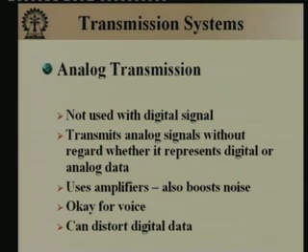So, it uses amplifiers, but the trouble with amplifiers, rather than the kind of regeneration that is possible in the digital world, is that it also boosts noise, whereas in the digital case we could take out the noise and regenerate the original shape of the signal. Here we can amplify it, so that if the signal becomes weak, we can make it stronger, but whatever noise is coming with the signal also gets amplified. So, this is okay for voice, but using analog transmission for digital data is usually not done, because we have so little control over the correctness of whatever we are sending.